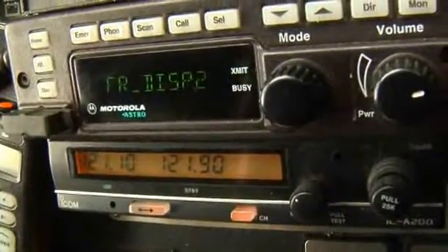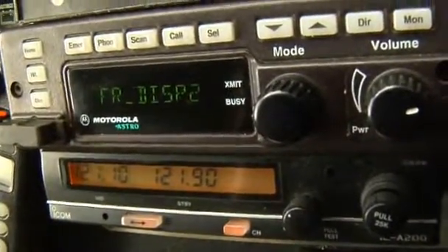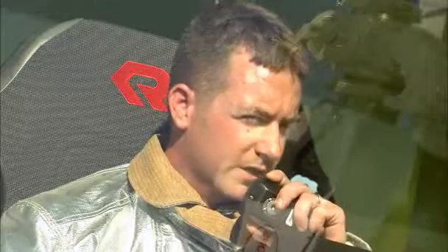If the frequency is busy during peak traffic periods, you may not be able to repeat the entire message. Read back enough to convey that you understood the message. Regardless of radio traffic, never hesitate to ask for clarification if you need it. Always hold your position until you have clearly understood the instructions issued.